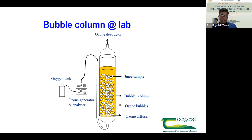How do we degrade various phenols, like colorants in colored water, to make it much cleaner, and to act as an oxidizer of the organic matter. So any negative feature over here can be used for another application. Another application we were investigating was using a starch solution. When starch was given ozone treatment, we were able to oxidize that starch, and its RVA, that is rapid visco analysis, of the pasting properties of that starch was completely different. So that means instead of using sulfuric acid or different acid treatments to oxidize the starch, ozone is the best candidate for oxidizing the starch.